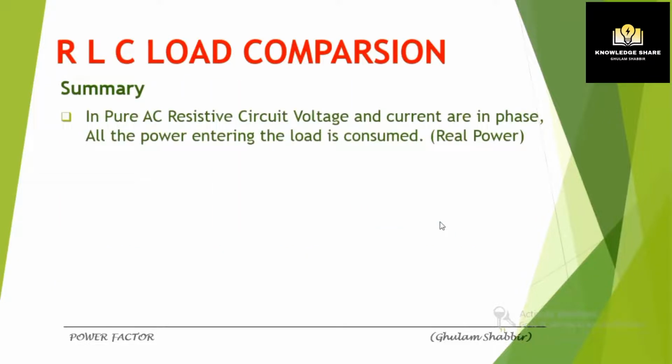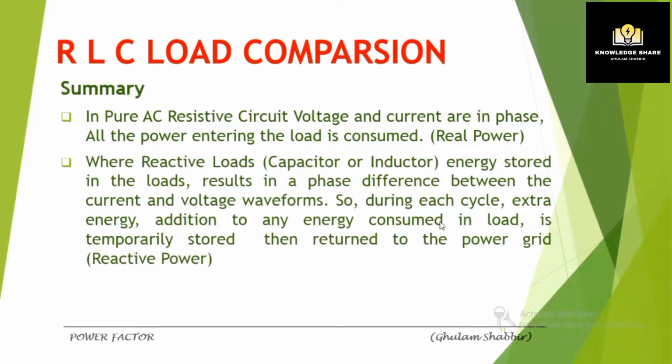So we can say in a pure AC resistive circuit, voltage and current are in phase. All the power entering the load is consumed. So this is what is real power. But when we have reactive loads, a capacitor or inductor, energy stored in the loads results in a phase difference between the current and the voltage waveform.